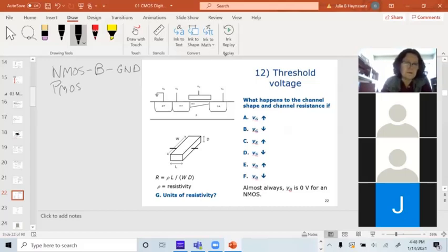Your multiplexer becomes an imager. For the PMOS transistors, we're going to tie the body to the highest voltage in the chip, which is generally VDD, and that will keep those diodes back biased. Remember, PMOS is built in an N well, so the N wells all get tied to VDD, the P substrates get tied to ground. And that's just to keep all the diodes back biased.